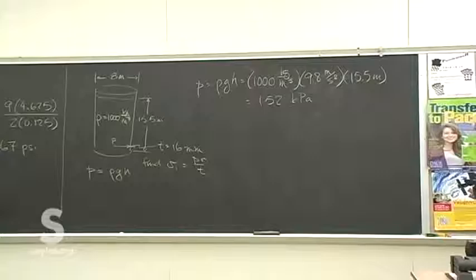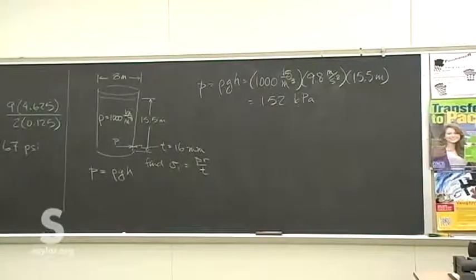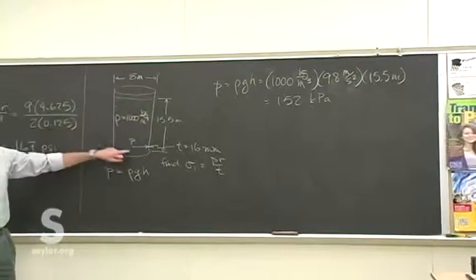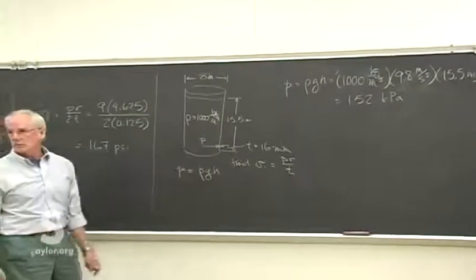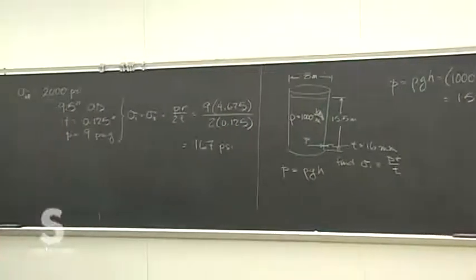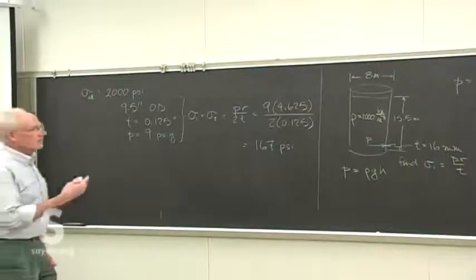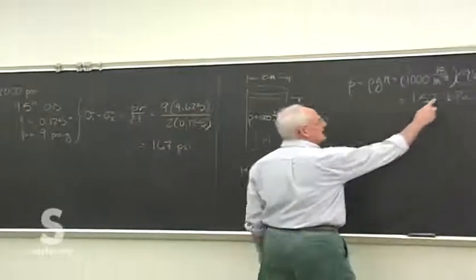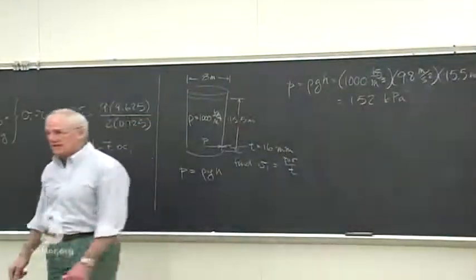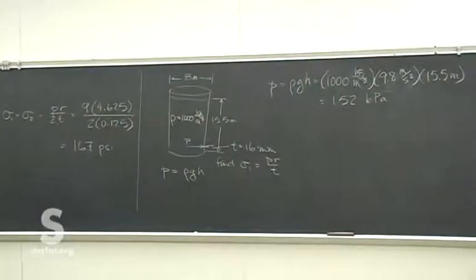Do we need to subtract the atmospheric pressure? No, that is the gauge pressure, because you're only worrying about the fluid column weight itself above that spot. So that, and there is no designation like kPa(g), at least none that I've ever seen, where it would be kilopascals gauge.